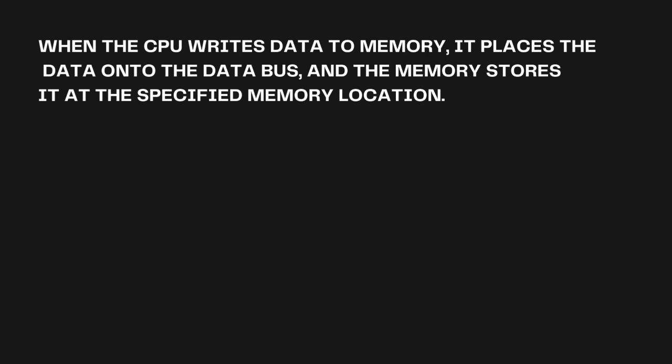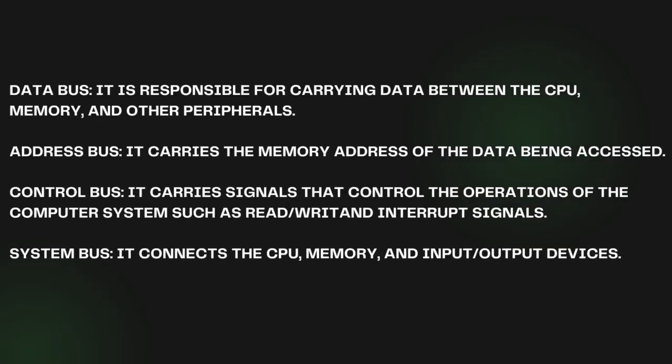One more use of the data bus is for shifting the data between different registers, like the data register or temporary register. Now let's move on to the length of the data bus. The length of the data bus depends upon the size of the word. Let's suppose the word size is 2 bytes, that means 16 bits, then the length of the data bus will be 16 bits. In this case, if the input data is 1 byte, meaning 8 bits, then the MSB of the data bus will become 0 and the LSB of the data bus will be set as per the input data.